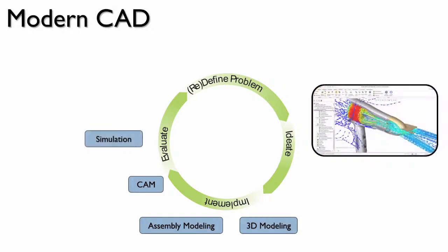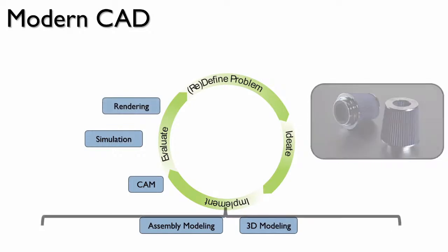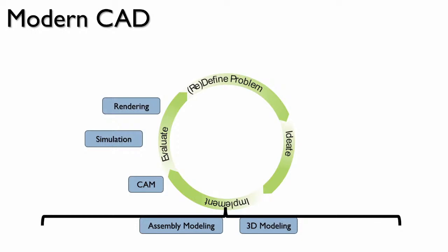Or you can do your evaluation through simulating things digitally, or maybe if you want more of a static evaluation, high quality rendering. The tools we generally speak of when we talk about a CAD tool are really mostly on this modeling side. And these tools get their power from working with two different representations, going from less concrete to more concrete: procedural CAD programs for defining the geometry, and then parametric geometry called boundary representations for capturing what that geometry is in a valuable way.